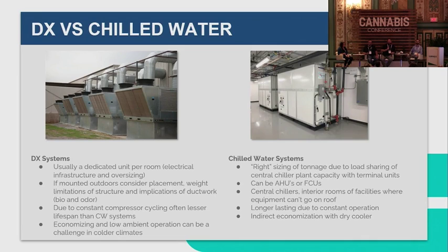And then with chilled water, water can hold many more BTUs per unit area than air. It's more dense than air. It's just a better thermal conductor. Chilled water systems really utilize an intermediate chilled water loop where we're cooling that loop to the right temperature in order to hit a dew point to dehumidify the air, and then pumping that water throughout the building.